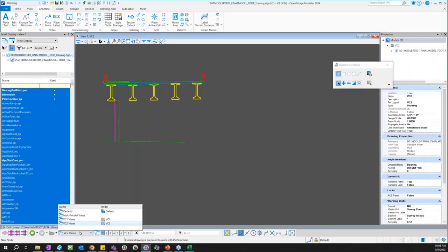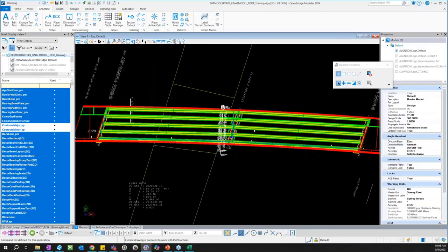It's super accurate and a lot easier than trying to guess sometimes and check various points depending on the longitudinal grade and the cross slope of the bridge as it relates to the longitudinal grade and the cross slope of the roadway underneath. Very powerful, takes the guesswork out of it. Okay, so that is it for the vertical clearance demo.